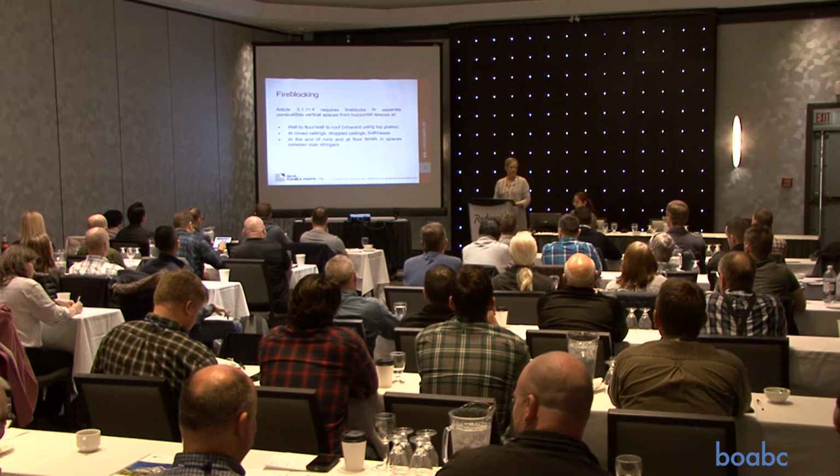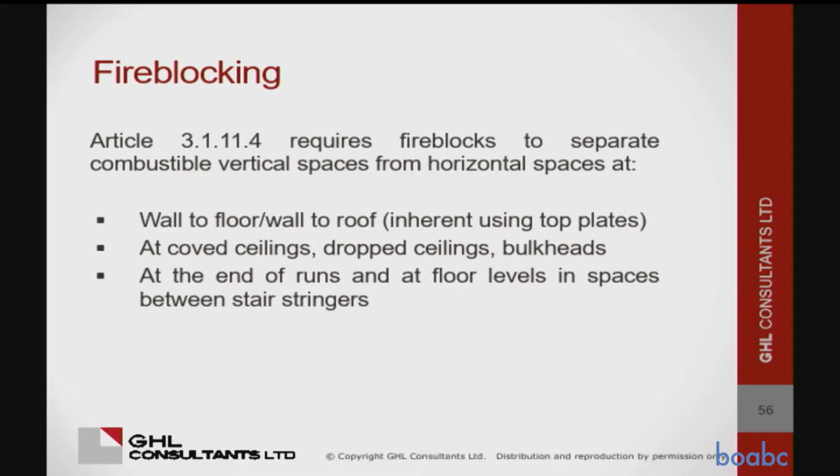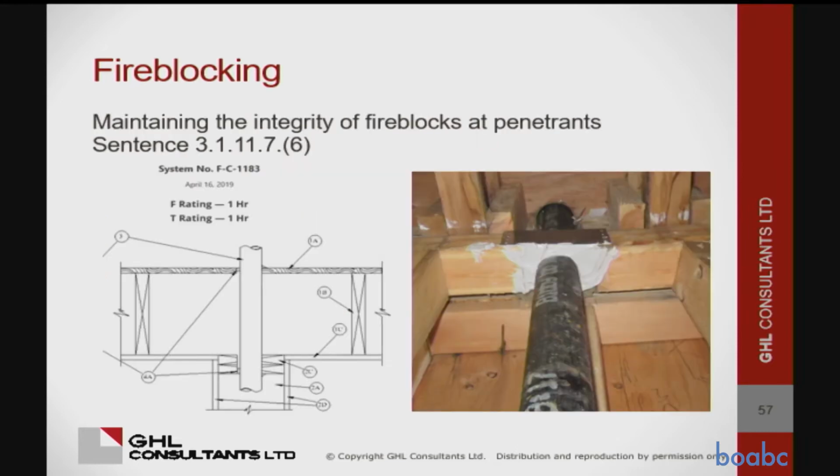And the other purpose of the fire blocking, of course, is to separate vertical and horizontal concealed spaces from each other. Wall to floor, wall to roof, typically inherent in wood framing using the top plates. Drop ceilings and bulkheads, you all know all this stuff. And then typically it looks like that. The code says if you run something through your fire block, you have to fill the gap with some material that will maintain the integrity of the fire block. The fire block being anything that'll redirect fire in a different direction for 15 minutes.